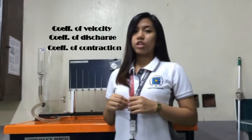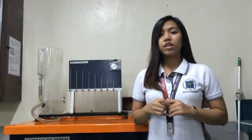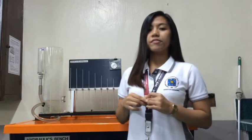There are three kinds of orifice coefficients: coefficient of velocity, coefficient of discharge, and coefficient of contraction. Coefficient of velocity and coefficient of discharge can be solved by dividing the actual value by its theoretical value, while the coefficient of contraction is determined at the vena contracta, where contraction caused by the orifice ceases. This activity aims to obtain data on the individual character of the orifice.